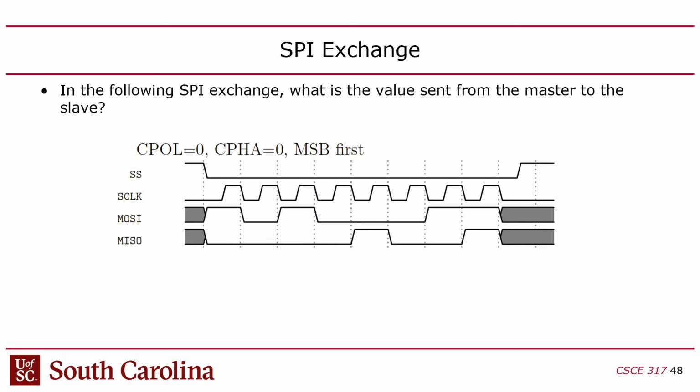Okay, now we have here CPHA 0. Don't look at this yet. If you can, I doubt you can, but just tell me, if CPHA is 0, what is the idle clock state? 0. Remember, 0, 0, 1, 1. And if CPHA is 0, which clock edge should you read? First or second? First.